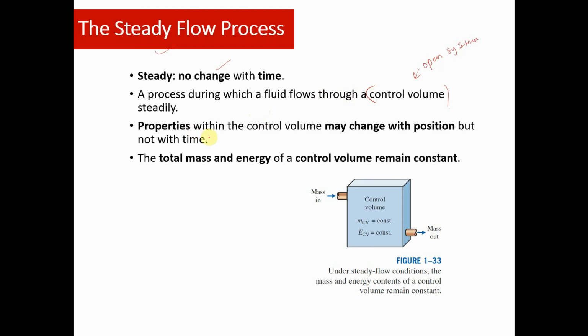With the assumption of a steady flow process, the total mass and energy of the control volume remain constant. That means the mass goes in and goes out, while the properties, including temperature, pressure, and so on, within the control volume may change with position but not with time.